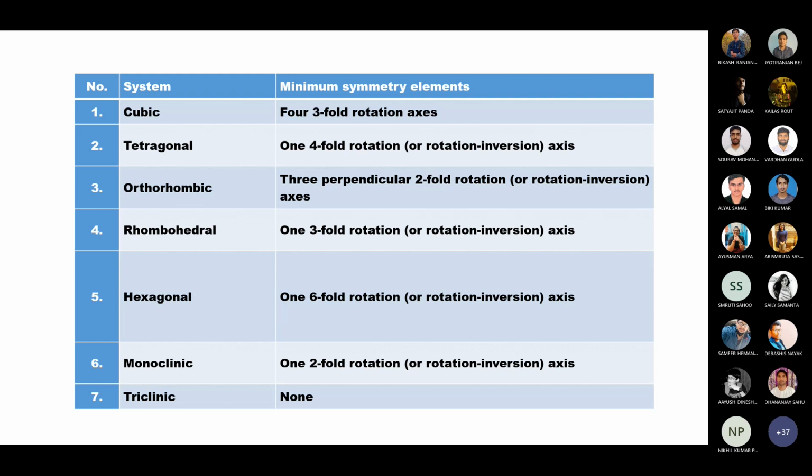So we generally concentrate on the cubic system, and sometimes the hexagonal close packed system, like magnesium, for understanding the deformation behavior of magnesium. But mainly we are going to focus on the cubic systems, body centered cubic and face centered cubic. A body centered cubic example is iron, and a face centered cubic example is aluminium or copper. And HCP, magnesium, a little bit.